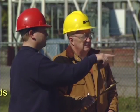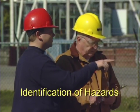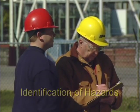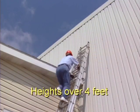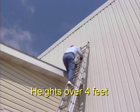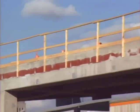A well-conceived fall protection program begins with the identification of all fall hazards in the workplace. As a general rule, anytime a worker is at a height of more than 4 feet, a fall hazard exists. When a hazard is found, 2 options are acceptable. First, the hazard can be prevented by eliminating it.